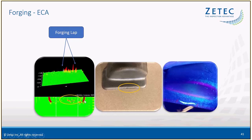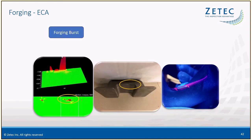You can see the scan here that the signals over here are the edges. So that happens when you scan across an area, you hit an edge, you'll get liftoff with the eddy current array. So it is worth knowing where you have liftoff and where you don't. But when you have known contact with that part, you're clearly seeing indications of this forging lap. And then the forging burst on the inside corner here is also showing up. And you can see, again, multiple things going on within that burst area, different depths and sizes.